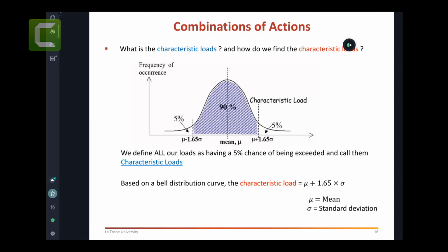developed. Those statistics will help us to determine what we call a characteristic load. There is a characteristic load, which is the load we actually take from the standard. So those loads in the standards, they're called characteristic loads, and they are taken based on these calculations. So the 1.5 from the table, or 3 for an office, or 4 for a university, whatever it was, it's called a characteristic load, and it came from applying this curve, the bell curve, and it's actually chosen at a point where we have a 5% chance for this load to be exceeded, right?